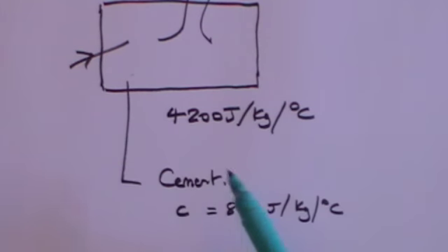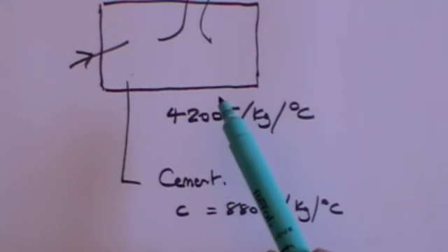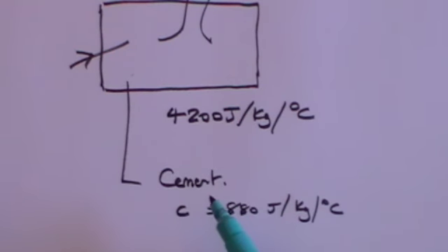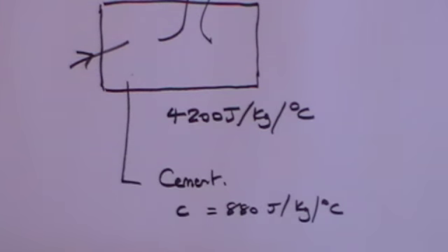So a night storage heater that's got cement in it will be smaller than a night storage heater that's got water in it. And you've obviously got to think about how big an object you want in your room, taking up room space. And it's a combination of the capacity and the volume of the device which determines what you use for your heat capacity medium.